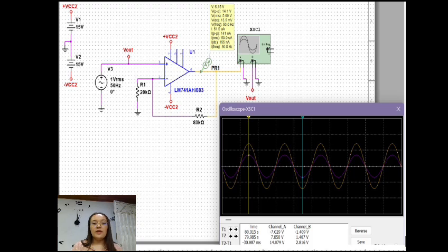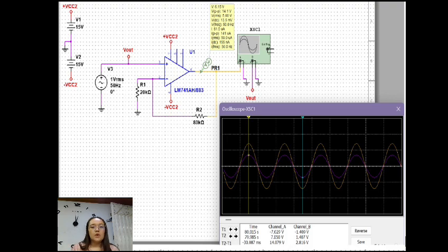Example assembly of the non-inverter. Necessary components: LM741 operational amplifier, resistors, power supply, signal generator, and oscilloscope. The connection to the inverting and non-inverting inputs: the positive input is connected to the input signal, and the inverting pin, the negative, is connected to a resistor network. Circuit continues.